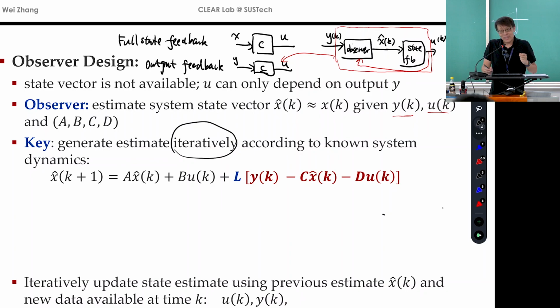Not for any U_k, but for any initial state, you can use a finite number of observations Y to determine that initial state uniquely. If that's possible, then you can compute the initial state and then use your model to calculate the state at this moment. That's one way to do it. It's not a very smart way, but it tells you the system is solvable. You can definitely get the true state. And the Luenberger observer is an iterative way to gradually find the system state.